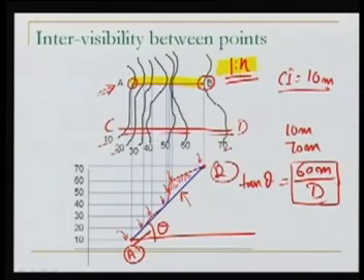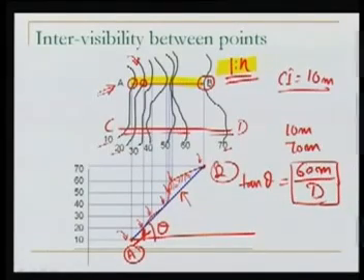Now, we can go to each contour and check whether this contour over here at 20 meter is obstructing or not. If it is obstructing, again we will find the height of the next contour, because what we can do here is measure the horizontal distance between these two. Whatever the horizontal distance is, small d, let us say, between contour of 20 and 10, that is the horizontal distance.